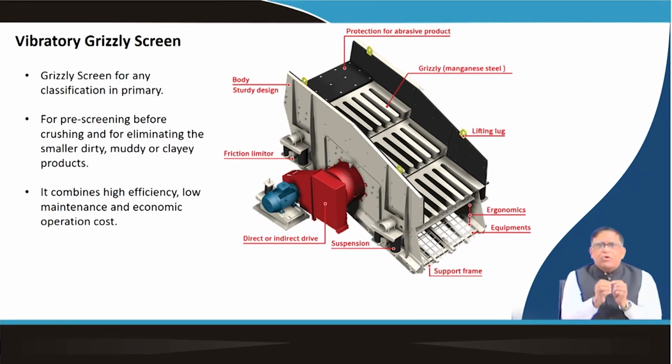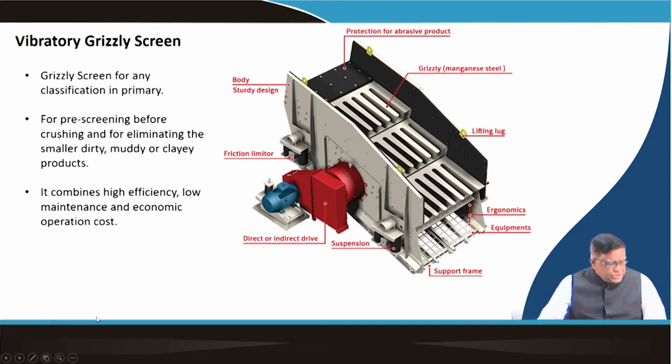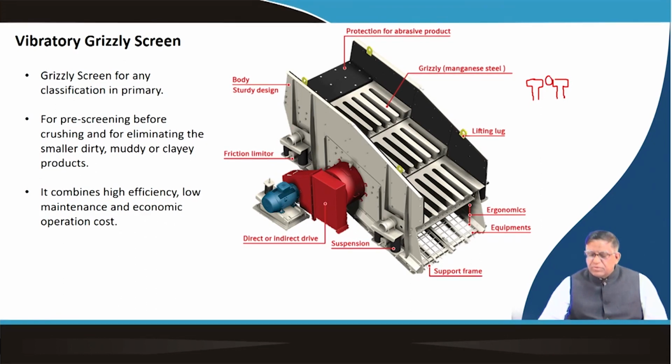So, if any rock mass goes over there, whenever any material is going, if your grizzly rods are of this type of cross section, then what will happen is that if two rods are making like this, the material once it is passing through this will very freely go through here.